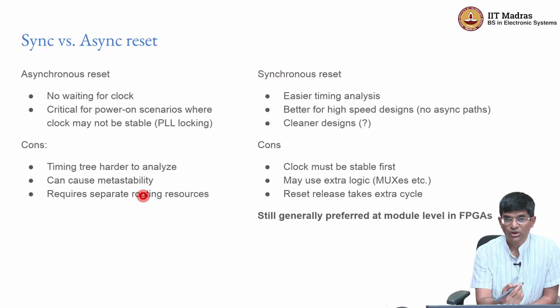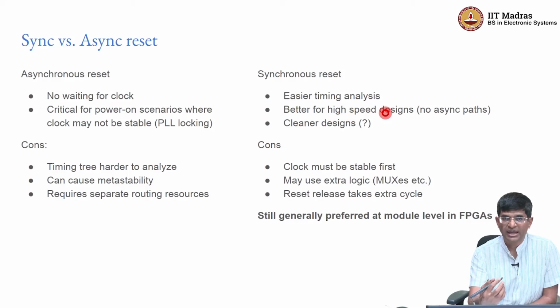On the other hand, synchronous resets turn out to be much easier from the point of view of timing analysis. They are more or less like any other regular signal that can be routed using the regular routing logic that is present inside an FPGA, for example. And especially for high speed designs, it leads to a cleaner analysis. You don't have so-called asynchronous paths, and all your timing analysis can be done in a uniform manner, right? What exactly is timing analysis is something that we will be looking at in a little bit more detail later.